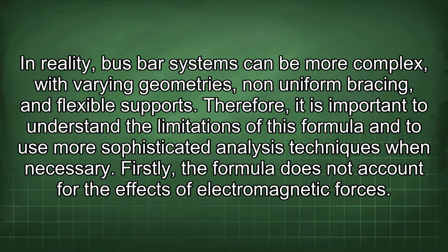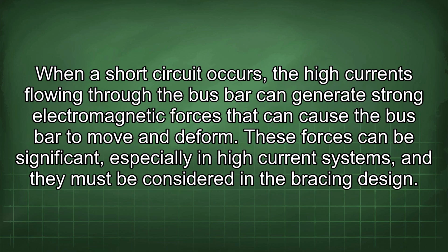Firstly, the formula does not account for the effects of electromagnetic forces. When a short circuit occurs, the high currents flowing through the busbar can generate strong electromagnetic forces that can cause the busbar to move and deform. These forces can be significant, especially in high current systems, and they must be considered in the bracing design.